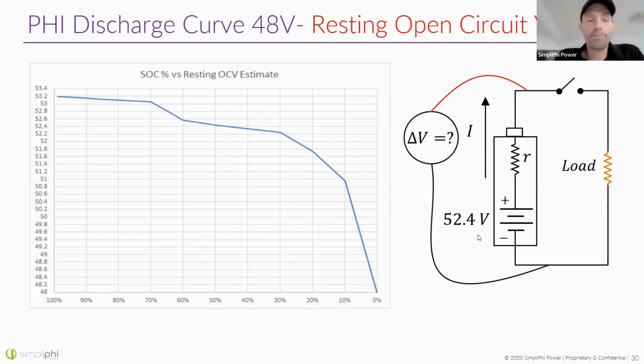The vent and battery case itself is susceptible to rust. We have a battery that's recently come in that saw salt spray, and so the case rusted, and with time, water was actually found inside the battery. So environmental considerations can lead to rust. These batteries are sealed fairly well, but you can't have them immersed in water or even have them continuously rained on if it's not an outdoor rated battery. So yes, environmental considerations like humidity, especially if you live near the coast like I do.